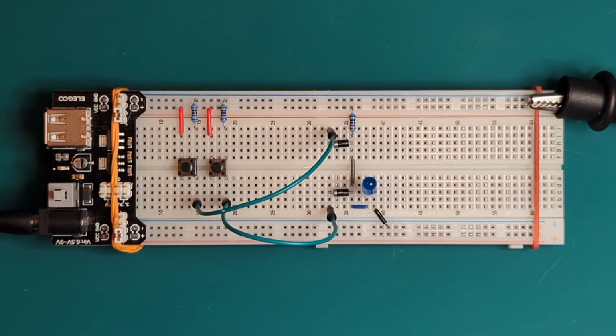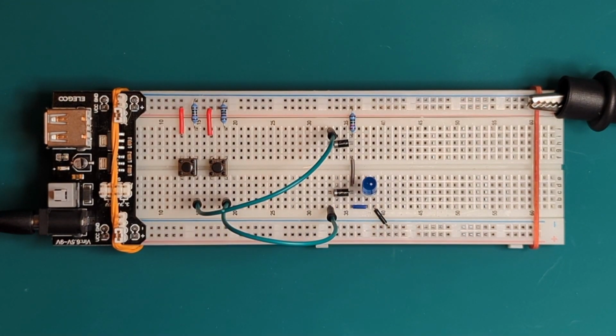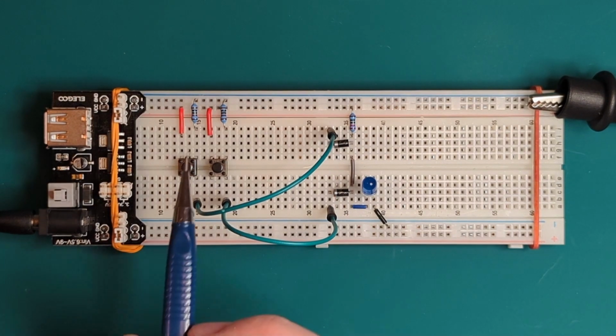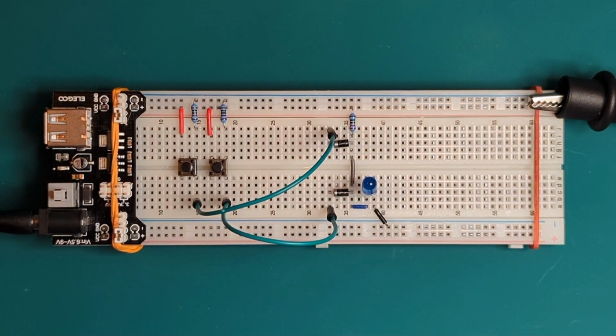How do we solve this then? We could fiddle with the resistor values, and that would mitigate the issue a bit, but the core problem would still be there. What we have found is a limitation of our gate. It doesn't play nicely with a pull down to low input. It still works fine with clean 0 volts or 5 volts inputs when I plug them directly to the rail.